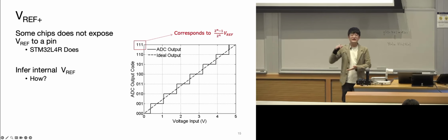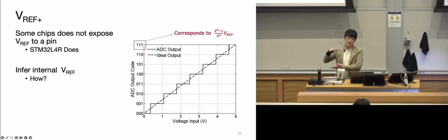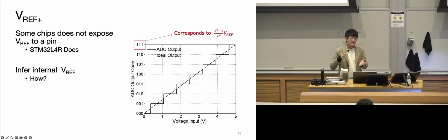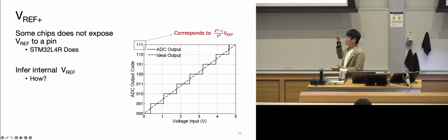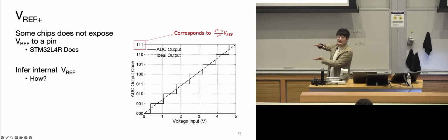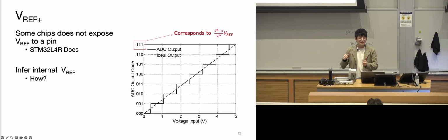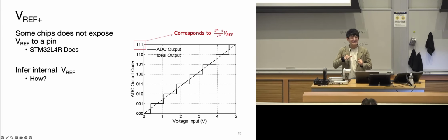It does not necessarily have to be the VCC of your system. It can also be a separate value, for example, half of that value if you have a voltage divider circuit somewhere. This is also quite common. You can essentially change the range of the ADC in order to maximize the sampling range. Does that make sense? Did I explain that right?